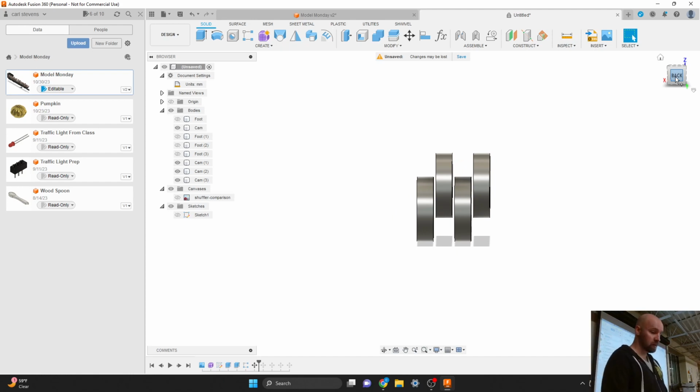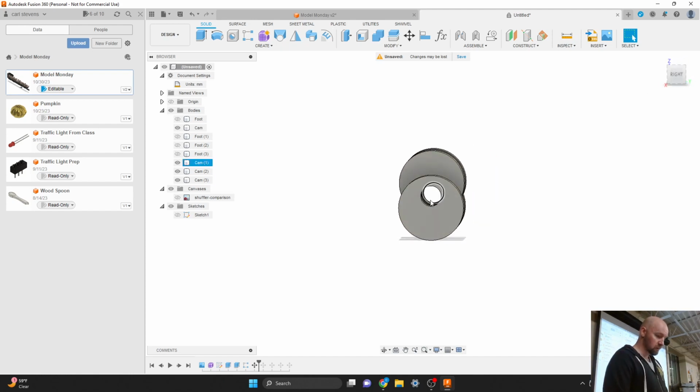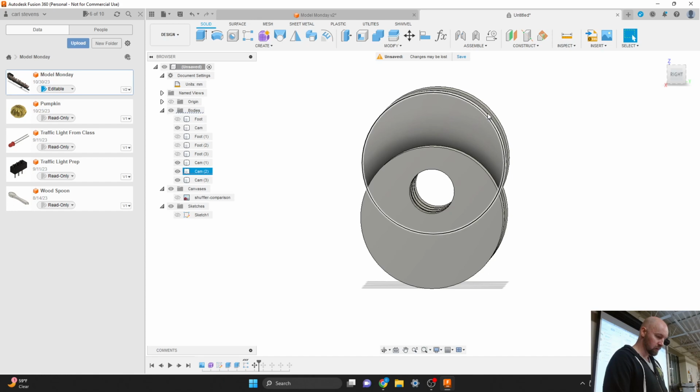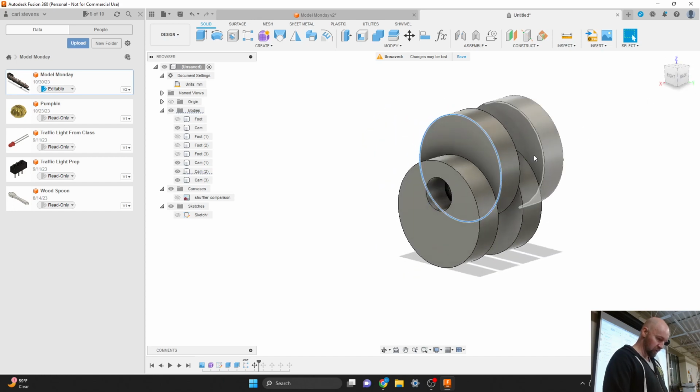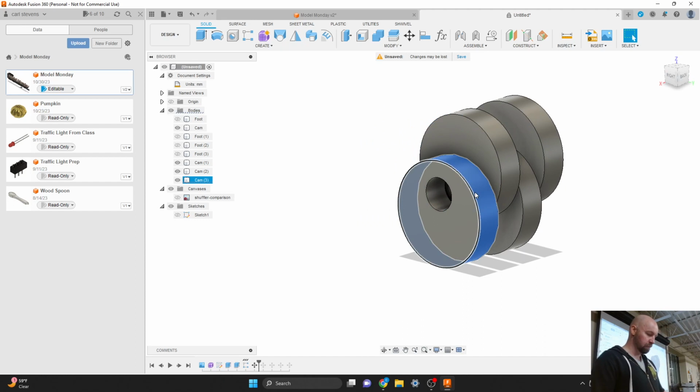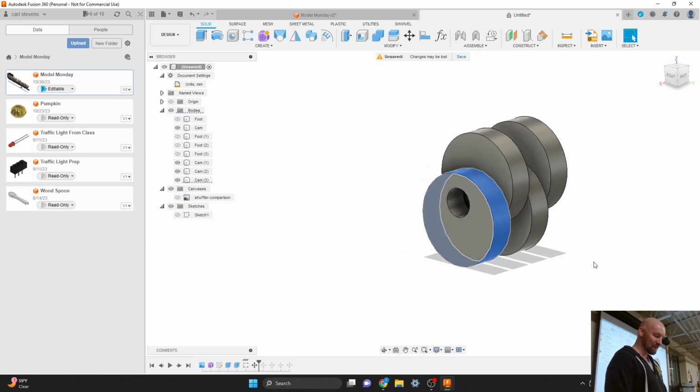You have a bearing around that cam. You put a little ball bearing, and the ball bearing is taking all the load. Well, the bearing would need to be out here, right? Yeah, it would be out there, but the bearing is pushing against the edge of your foot. There's not a lot of room for a bearing in this thickness. And I don't think you want a bearing anyways, because that's going to be heavy. You think so? Yeah, it would be too heavy. There are kinds of plastic that are nice and slimy. Not nylon. You're going to want not nylon in this case, like Delrin or something. Yeah, Delrin stuff. I'd have to have some of that.